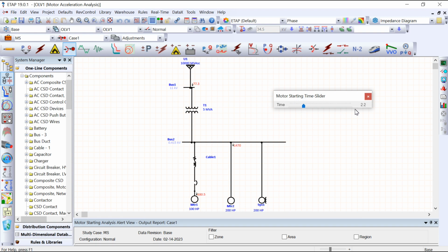Then when we started on the 2 second, we started motor 2, and you can see it's also a very big starting current on motor 2. And you can see motor 1 continuing to decrease its current. Then both of the currents will drop until they become normal.